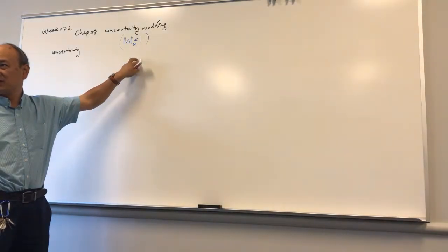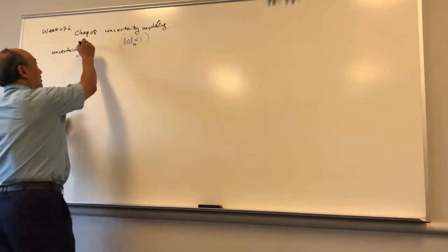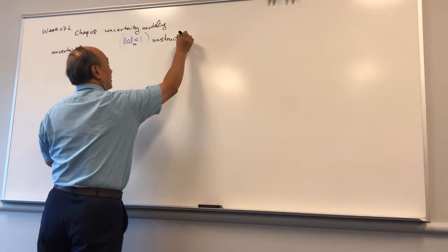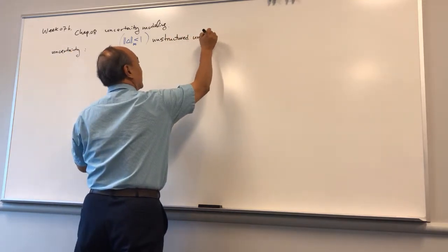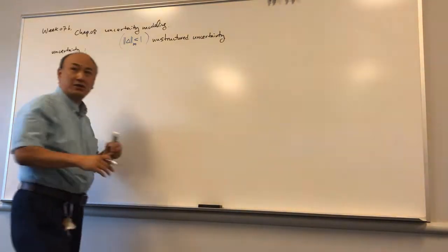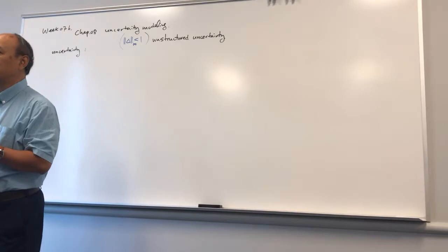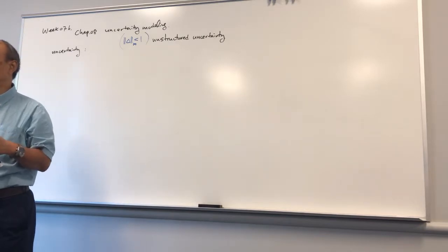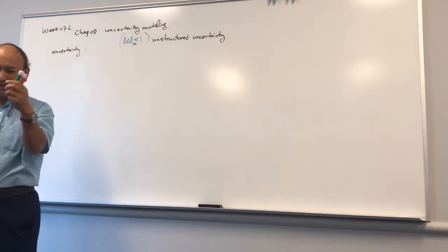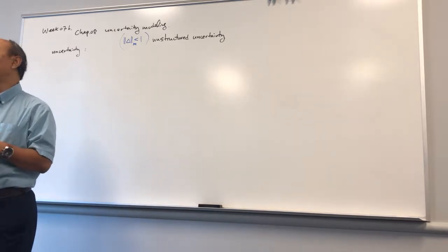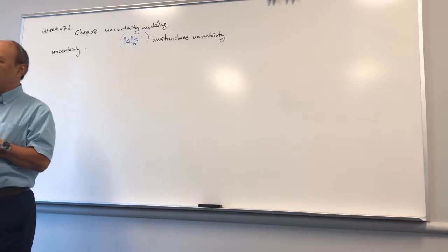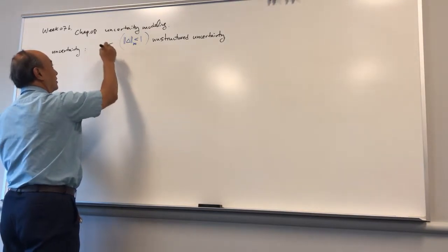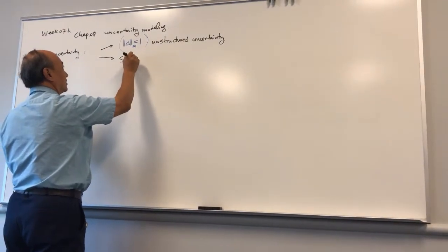So this type of uncertainty actually is called unstructured uncertainty. There's no structure in that uncertainty. We don't assume anything. It's just like a black box. We know it's bounded, okay? But inside the box, what's the structure? Is it like diagonal or fully populated? We don't know. We don't assume. What if we can see through the black box and know something? That is called structured uncertainty?